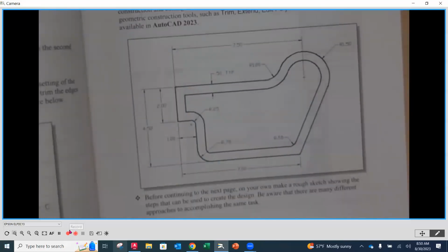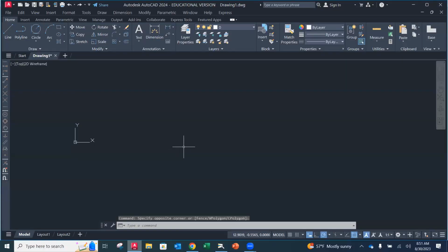All right. So again, we're going to highlight the polyline command. So I want to be sure that we're using that. So whether you start your 0,0 in that bottom left-hand corner, let me think. Do we want to do that? Yeah, I think I am going to start that because then it's going to be easy to place my circle later on. Okay. So I am going to start my 0,0. I don't know if it's exactly there. Sometimes it moves around. So when I start my line command here, even though it's in that upper left-hand corner, I'm going to click my line command, go down into my drawing area, and I'm going to specify my base point as 0,0. Enter. Okay. So it did grab that.